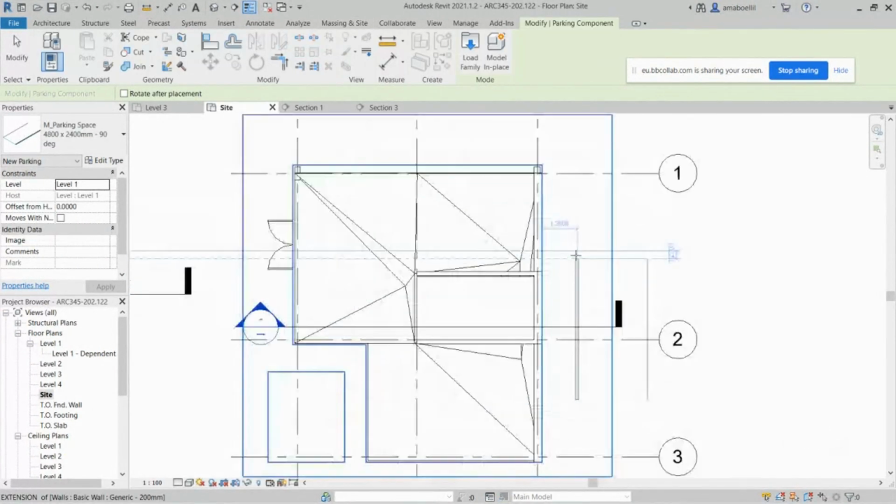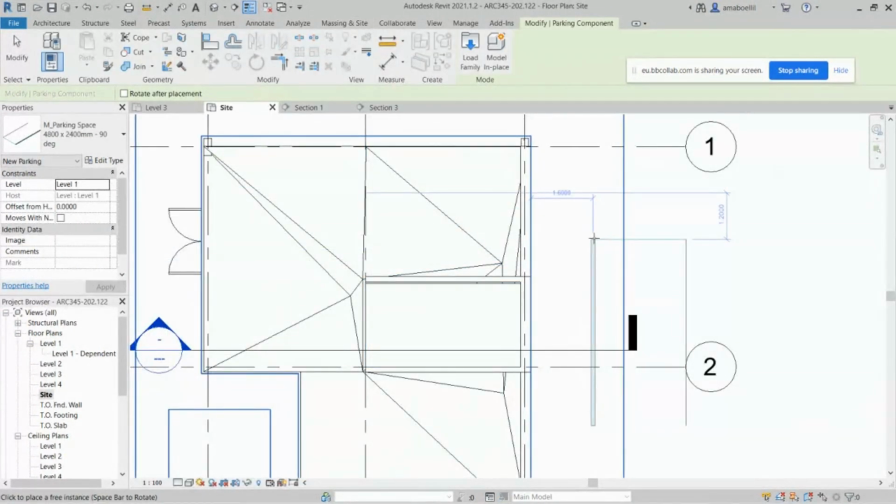and then start to put them side by side. And of course the size here also, the building is maybe you have to adjust the proportion, adjust the dimension of your curve and your dimension, and of course you can extract this number from the standards that you have. And usually the parking lot is about 2 by 5, or a little bit more than that, maybe 2.5 or 3. You can see different parking dimensions.